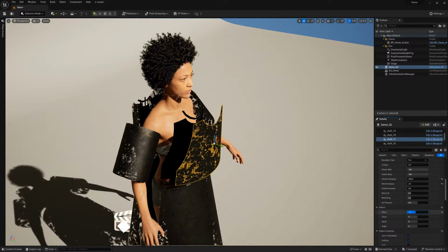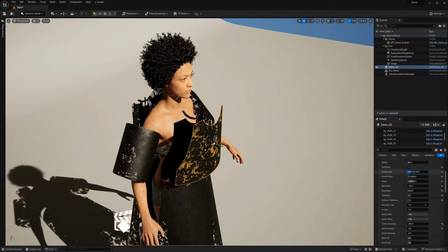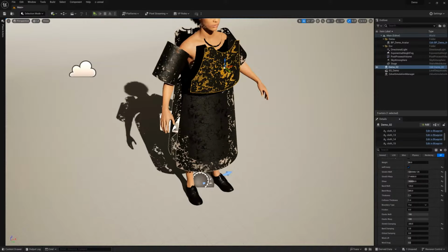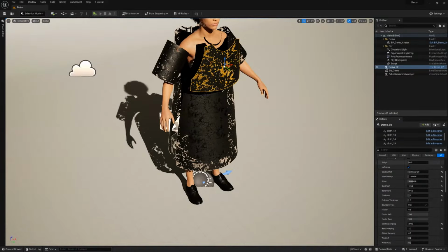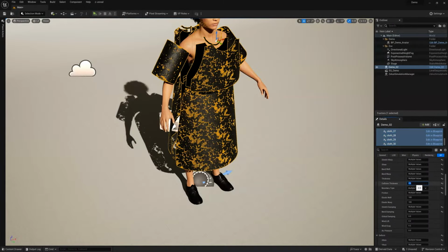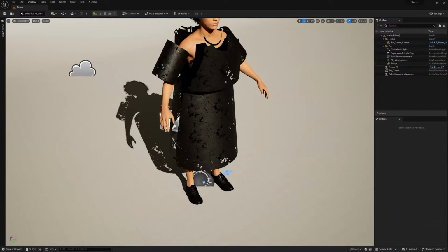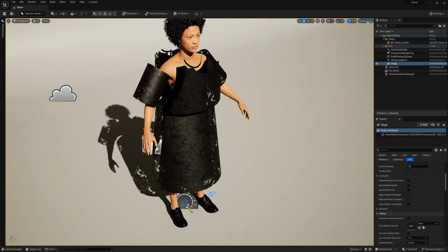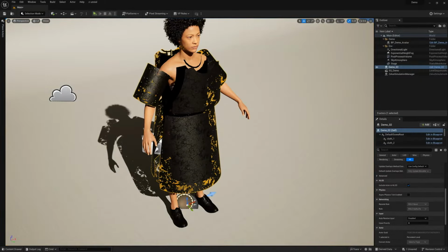And also, if you want to make it more stretchy, you can change this value here. No need to go back to GWeave. At this time, I'm going to increase the collision thickness for a more realistic result, to 2, and I'm also going to set this down to 1.2. So these are essentially the physics properties of the fabrics that have come in. Yes, it is. We're not stuck with what got done in the GWeave tool.